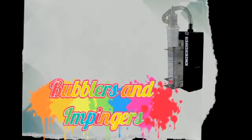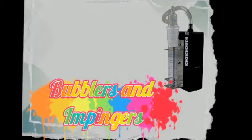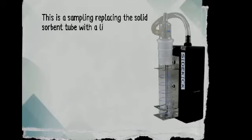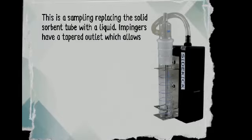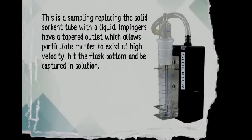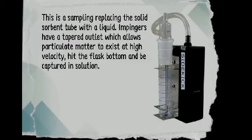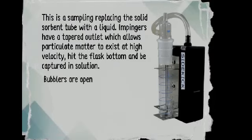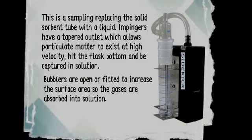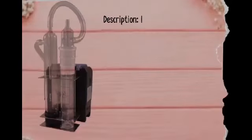In this video, I will be discussing the other type of air equipment, which is bubblers and impingers. This is a sampling method replacing the solid sorbent tube with a liquid. Impingers have a tapered outlet which allows particulate matter to exit at a high velocity, hit the flask bottom, and be captured in solution. Bubblers are opened or fitted to increase the surface area so the gases are absorbed into solution.